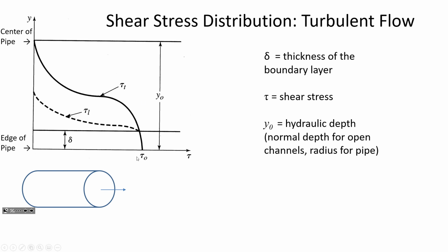And so the takeaway message from this is just the distance that shear stress is exerted, depending on, for example, if the bulk flow is turbulent or if the bulk flow is laminar. Obviously, if you have higher velocities and there's turbulent flow, then the shear stress is going to extend further into the pipe. Any questions about the things that we've been talking about so far, the idea of a laminar sublayer? Any questions about that concept?